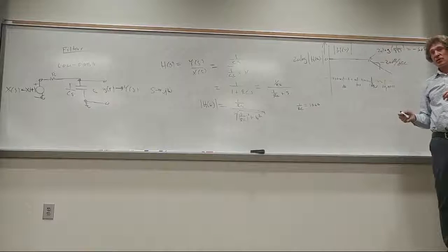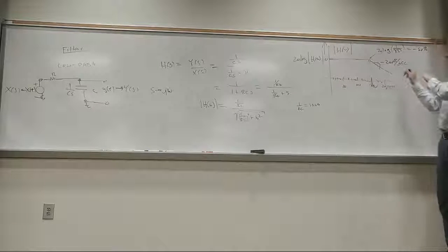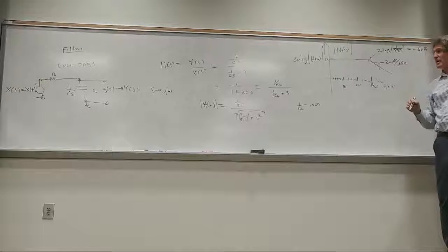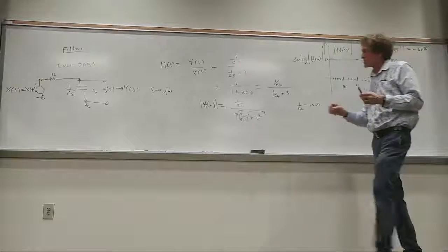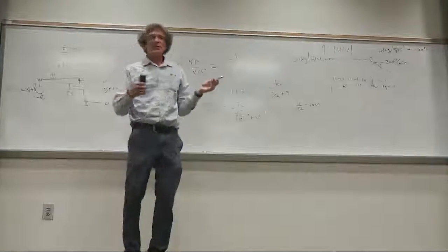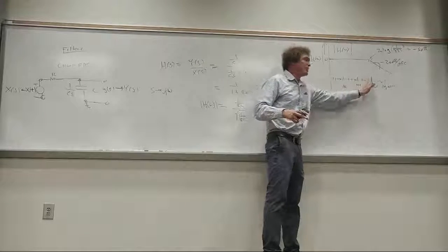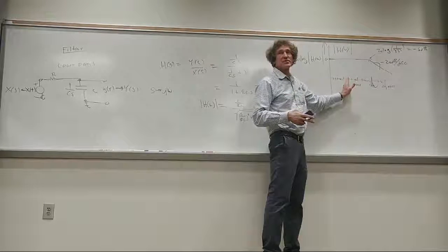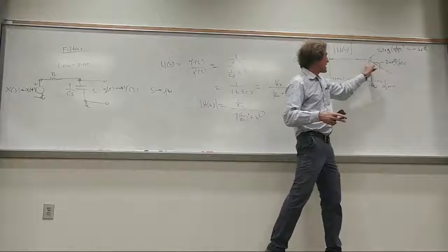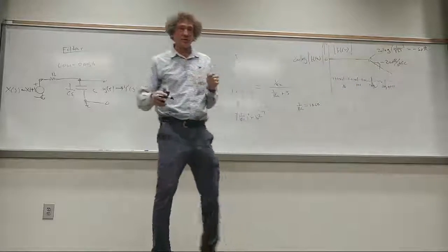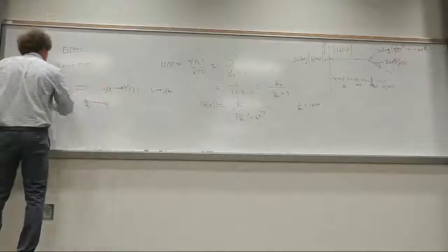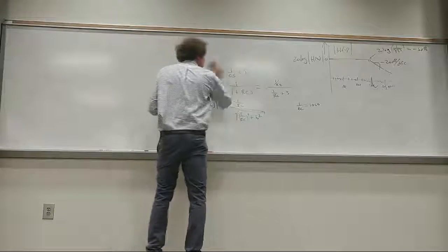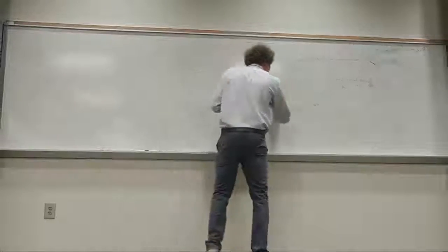Now suppose we're going to apply this exact filter. We want the same behavior for a sampled signal. Follow me? This is the bilinear transform, so I'm going to try to show you that. I want to put the filter up first so you get an appreciation. And you all agree that we could make that low pass cut anything we want. 1 over RC dictates where that frequency is, correct? You choose R and C, you can make it as low as you want or as high as you want. But the general shape will always be the same. We just shift where that cut frequency is. Agreed? All right, now, how would you do this with real digital filters or discrete time filters?